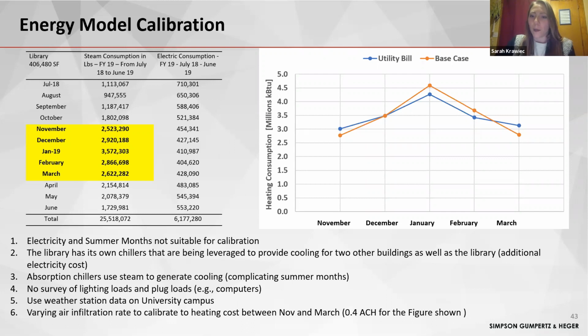Okay. Another question, or Greta, did you have something to comment on? It sounded like you used spray foam insulation for the added insulation, so that's great at air sealing, kind of answering Richard's question. Where we were rebuilding the wall, we would have had a dedicated air and vapor barrier there, since we would have had access to it. But you're right, there was a portion of the wall that was pretty much mass concrete with a little bit of insulation on the outside, and that's where the spray foam would have been to help improve the air barrier there.